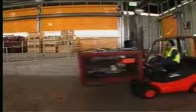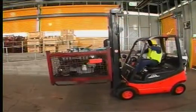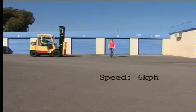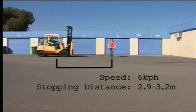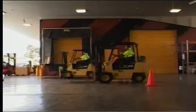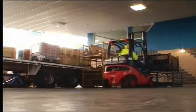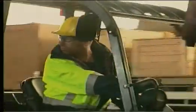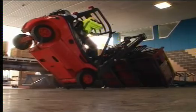If you brake too quickly, the result is dynamic instability and a tip over. Even when traveling at 6 kilometers an hour, it will take you 2.9 to 3.2 meters to come to a safe halt. This distance may double if you're distracted or traveling on a slippery terrain. Accelerating backwards too quickly can cause the center of gravity to move outside the stability triangle, resulting in a forward tip over.